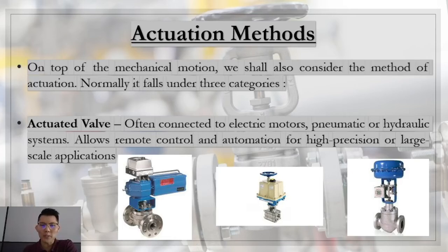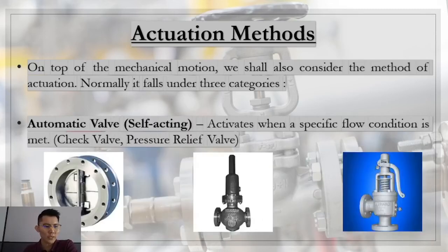Yes. So for example, you have an actuator, but in case there's a failure, for example there's no signal, or there's no pneumatic supply, meaning no air, or the hydraulic system fails, you couple it together with the gearbox to perform a manual override. It means if it's out of control, you cannot use automation or remote control, so at least you can attend to it using the hand wheel. Okay.